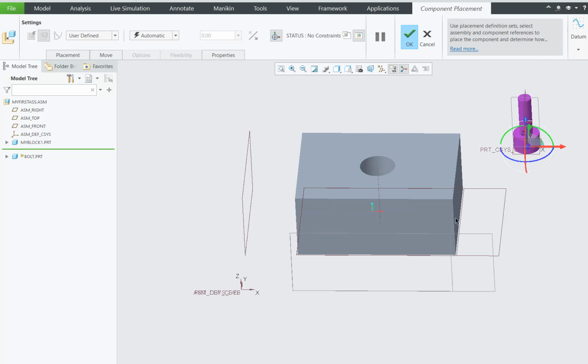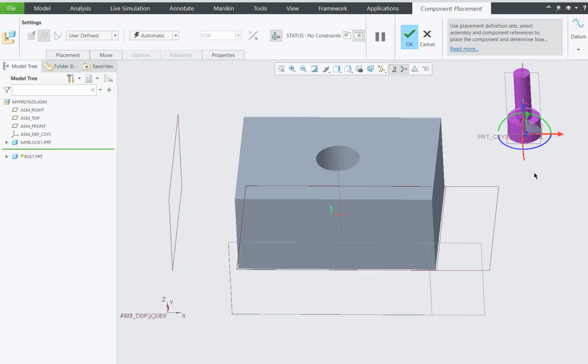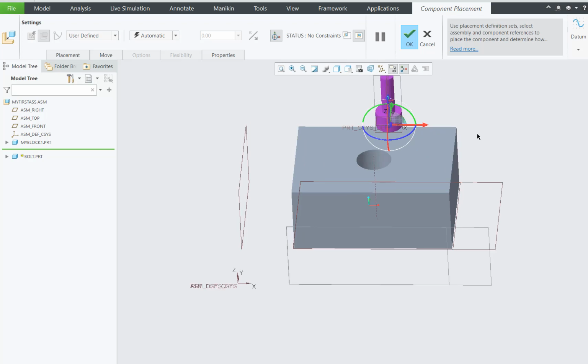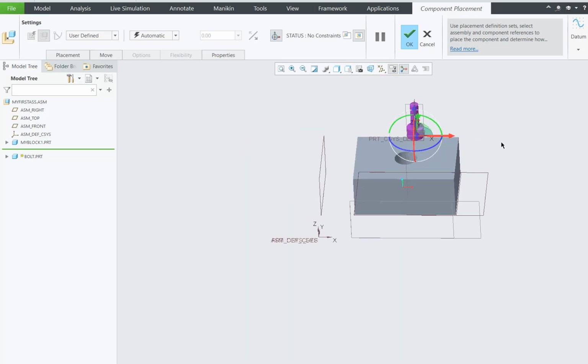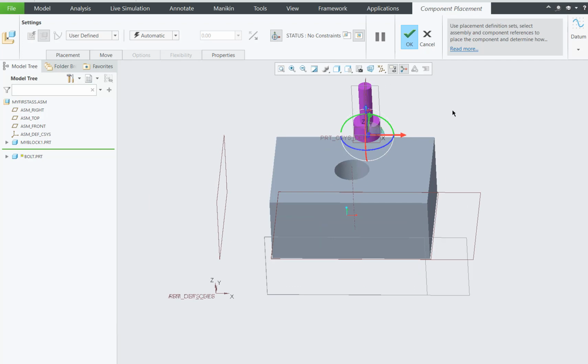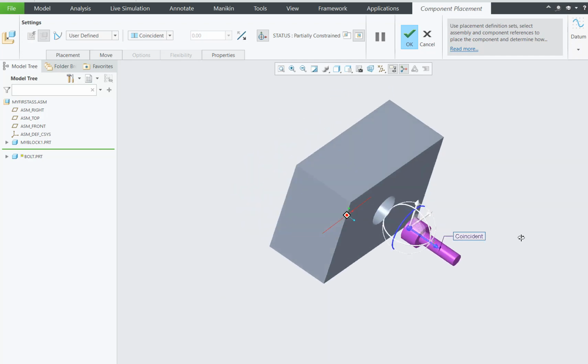Okay. Now it came in virtually here, so we can hold left click and drag wherever we want to see, and we can use the middle mouse. So now we can translate until we get a convenient view to assemble them. Okay. Now I'm scrolling the middle mouse. So what you do is, now you select this, pick that, and if you pick this, it will align them. As you see, with the middle mouse, they are aligned.